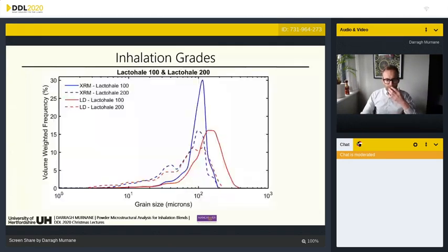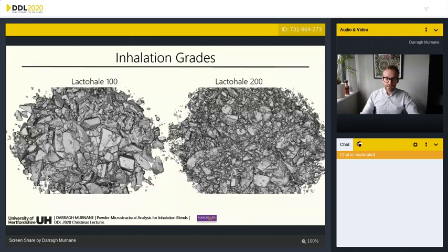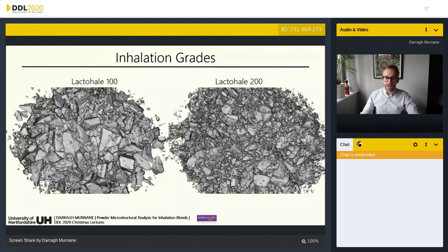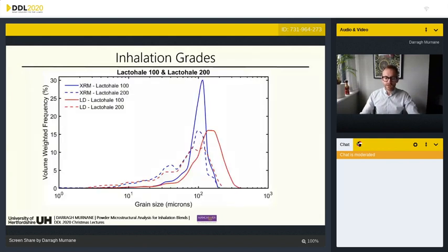Well, because we're able to identify every single individual particle within that 3-dimensional matrix, we're able to measure out the volume of that individual particle, and from the volume of the particle, we're able to work out the diameters of the individual particles present. So in a non-destructive way, we're able to take images such as this in 3 dimensions. We're able to work out the volumes of the particles and therefore a volume distribution of the particles, or a particle size distribution.